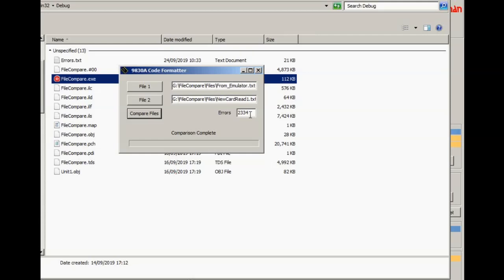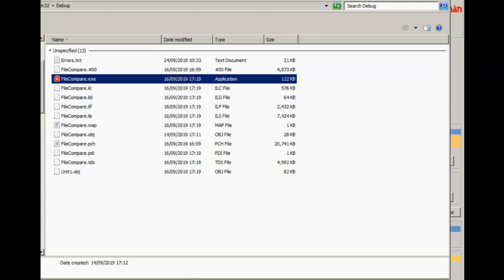It's just because the dump file that I've constructed, I haven't included the last EEPROM image. And again, that was intentional as a sanity check to make sure that as I go through all this, I'm picking up errors only in the correct place. But if we do the comparison again, you'll see that for the bulk of the comparison, there are 0 errors. In other words, we're looking all the way through the file up to the end, and until we get to the end where we expect to see errors, there aren't any. And as I say, that's a good sign. It means that we are essentially getting exactly what we're expecting.